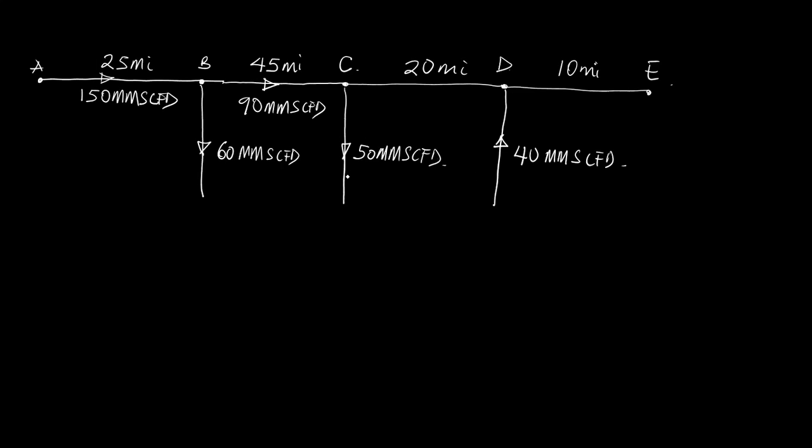Taking out 50, it will now remain here 40 million standard cubic feet per day. Since 40 is coming in, 40 is going into this point, that means the one terminating here at E will now be 80 million standard cubic feet per day. So now this is how the diagram will look.